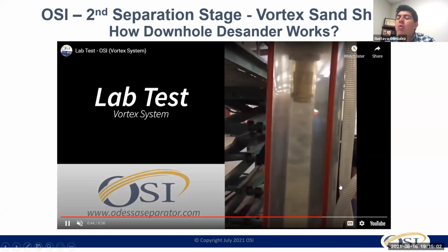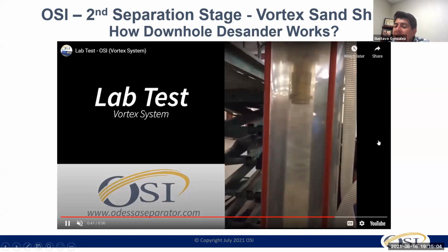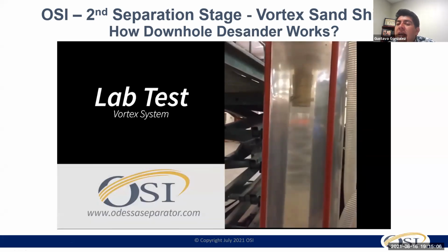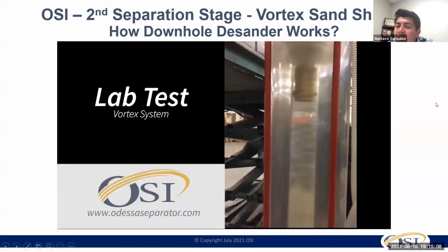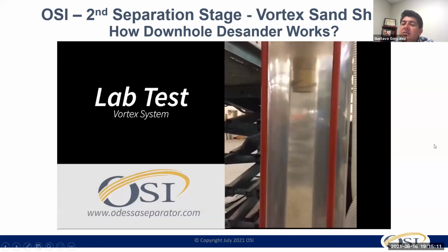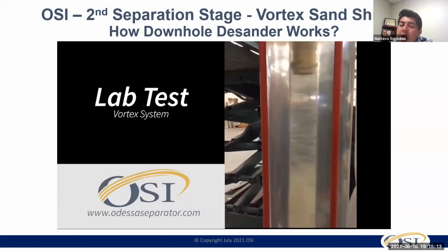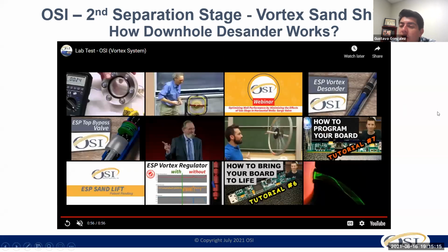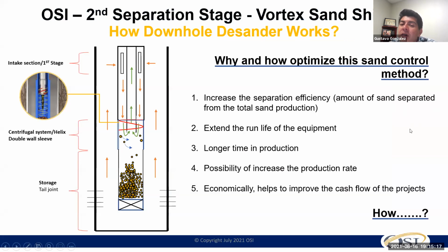What we're doing here, and what we always recommend, is to delay the process. Once again, instead of dealing with all the sand at once, let's delay that process and break those 300 pounds, 200 pounds, whatever it is, down to the point that my ESP or rod pump can produce it without causing damage to my system. So again, it goes back to extending runtime, longer production time, increasing the production rate, and helping the economics.